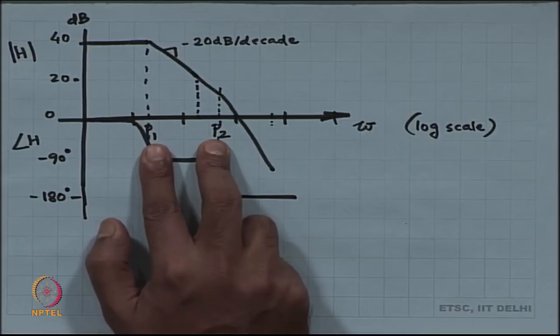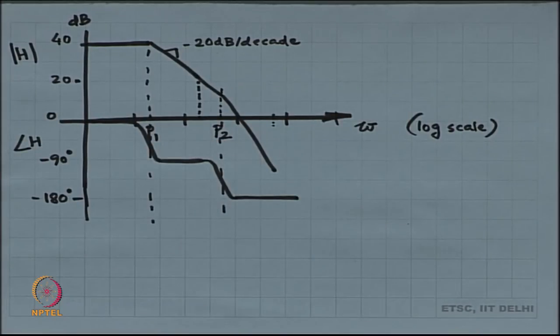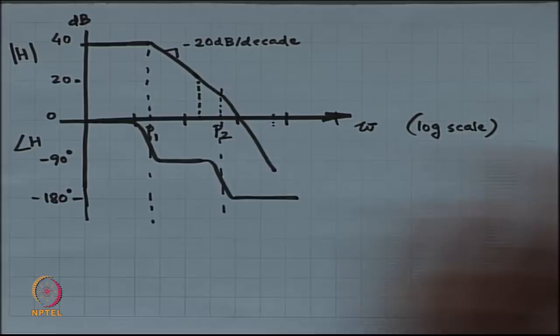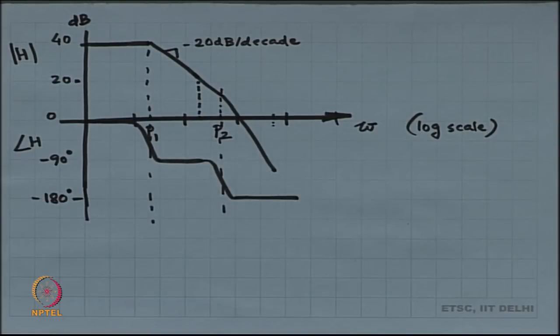If P1 and P2 are in the right half plane, then, sorry, nothing works. If a pole happens to go to the right half plane straight away, then do not bother, that is no good. Now, the assumption is that P1 and P2 are already in the left half plane. Given that, the op amp by itself is going to be stable.